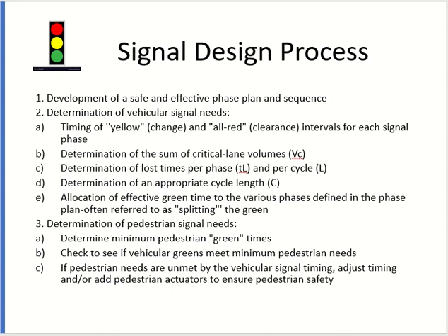Okay, so you can allow different movements in one phase, it is good, but these movements should not be conflicting. Last time I gave the example: you can allow one going towards east and the one going towards west. You can combine them, no problem. This is effective. Or you can combine one going straight and one going left. This is effective, and it is safe as well. Both these options are safe.